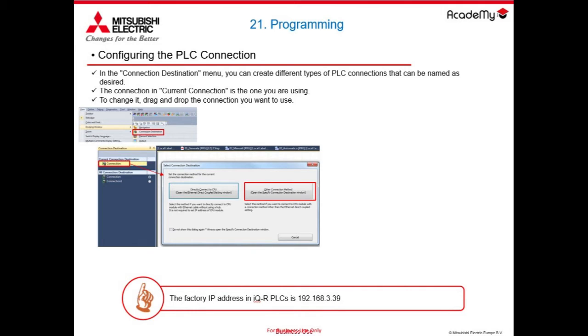Network in the same sector, PLC types, we can continue working in DHCP. For the connection via hub, instead, we put our PC, our network card, in the same IP class as our PLC. At that point we can connect to the PLC through IP.